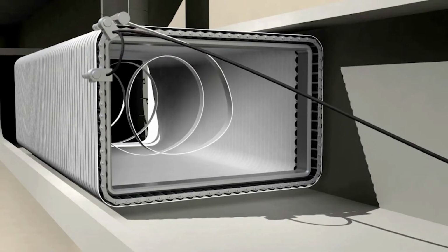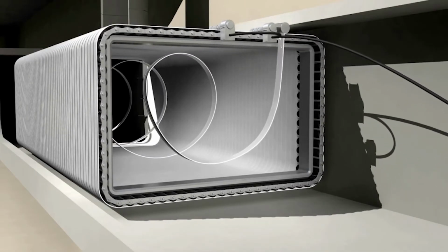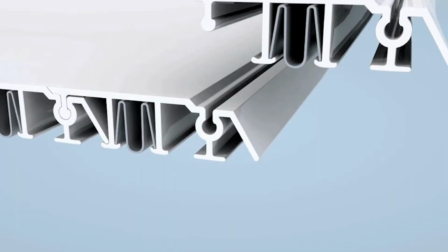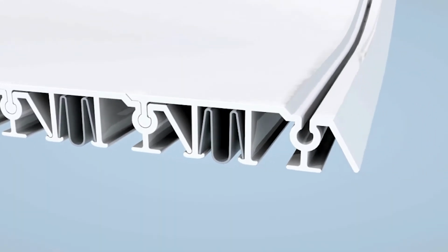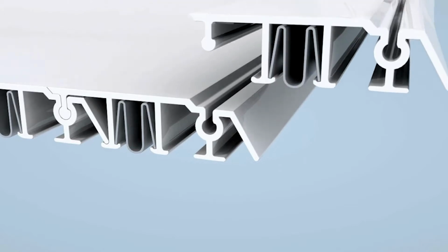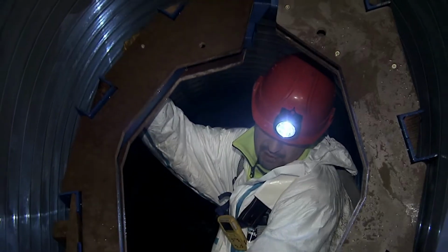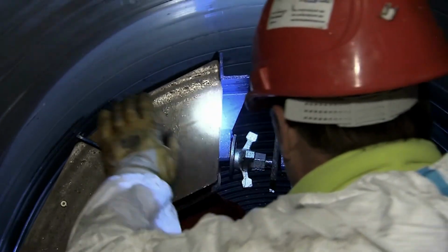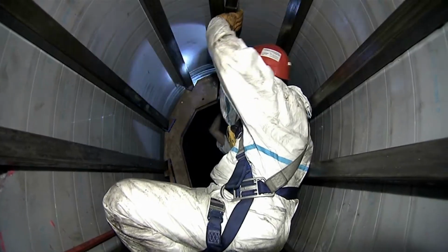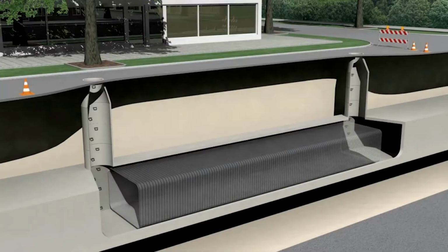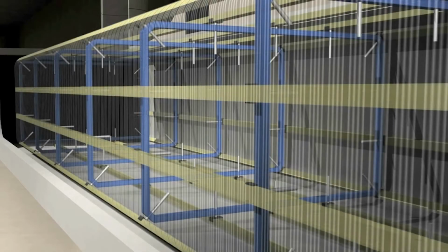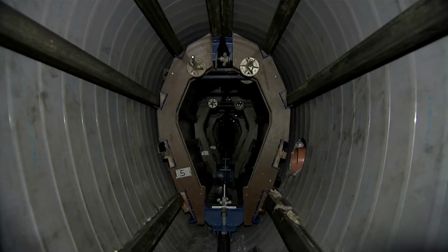The interlocking edges of the profile create an impermeable mechanical lock. Optionally, a steel reinforcement can be used to withstand strong deformational forces. The bracing system is set up to provide structural support during the grouting process and positions the SPR profile in the host pipe according to engineering specifications.